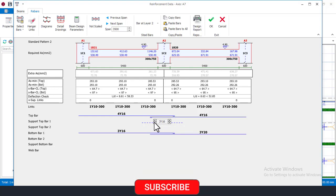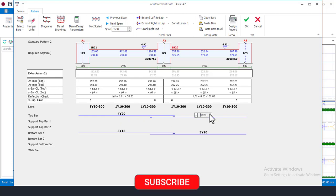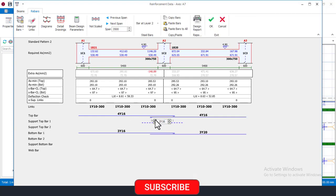Or we can choose to remove this entirely and then increase this to Y20 and then Y20 and all that. Okay, this is okay to have straight, but like I said, you take the cost into consideration. So having 4Y20 all through at this top here is more expensive compared to having Y16 and then coming here to put just three bars here and call it layer 2. So this is cheaper compared to having 4Y20 all through.